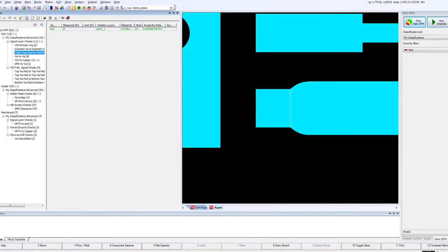Valor NPI add-in is the best way for a PCB designer to review troublesome manufacturing-related defects such as copper and solder mask slivers, exposed copper, line width and spacings based on layer copper weights and layer positions, all within the tool you are accustomed to using, Expedition.